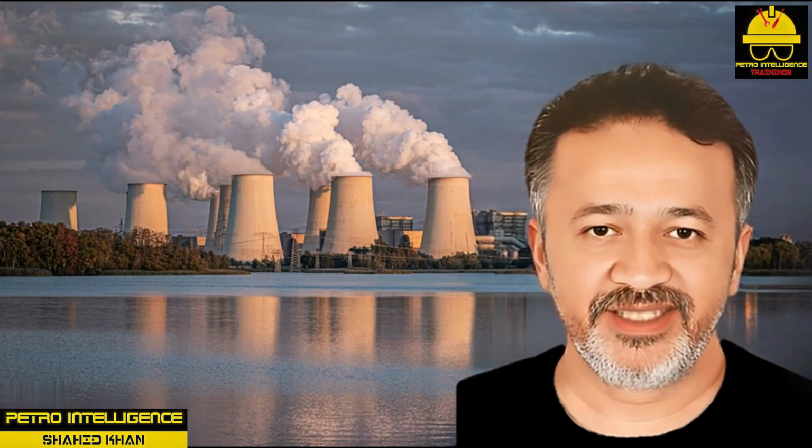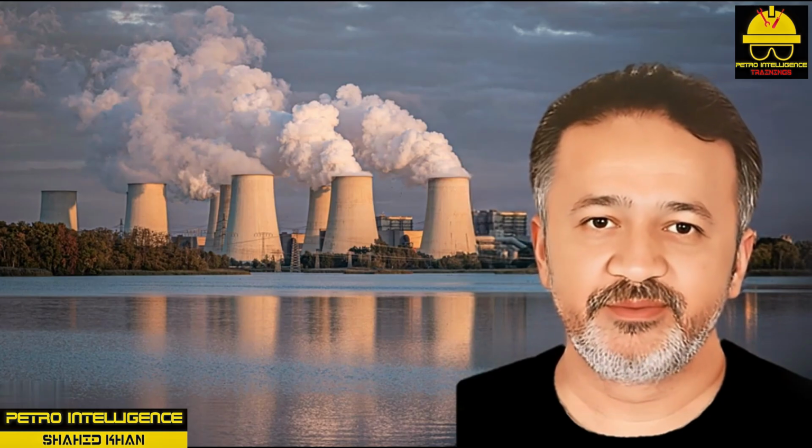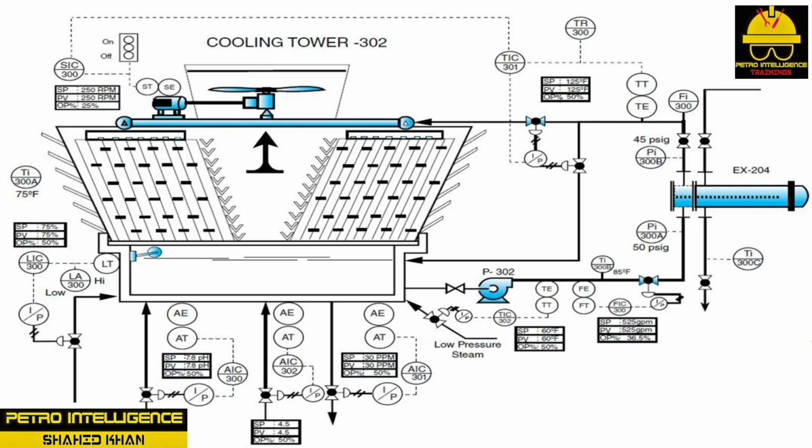Suspended solids, exchanger tube fouling. As air circulates through the cooling tower, it carries solids in the form of small dust particles. These solids are captured by the downward flow of water and collected in the catch basin where they form sludge. Sludge is removed through the blowdown system. Suspended solids can build up inside the tubes of a heat exchanger and cause fouling. Fouling is a term used to describe restriction or plugging.